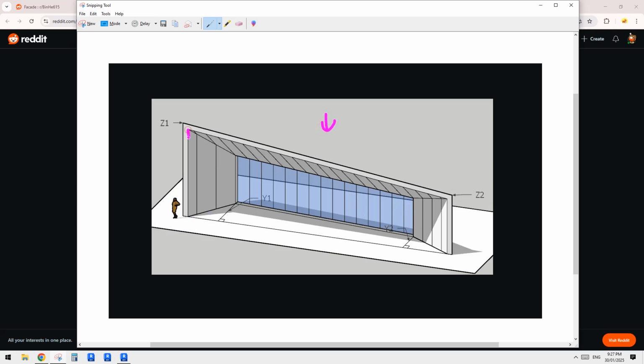We're going to place 1, 2, and 3 reference lines there, and then we can place another 3, so 1, 2, and 3 reference lines using the curtain wall, because we can just pick a work plane on the curtain wall and pick lines.